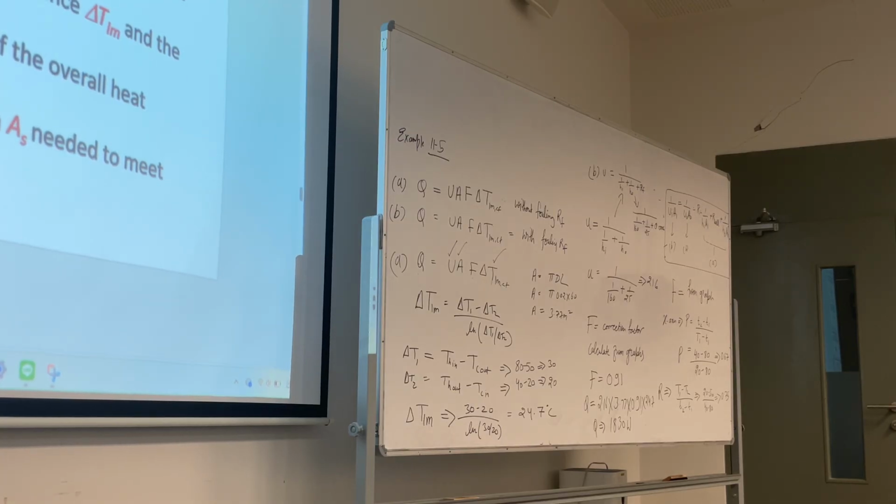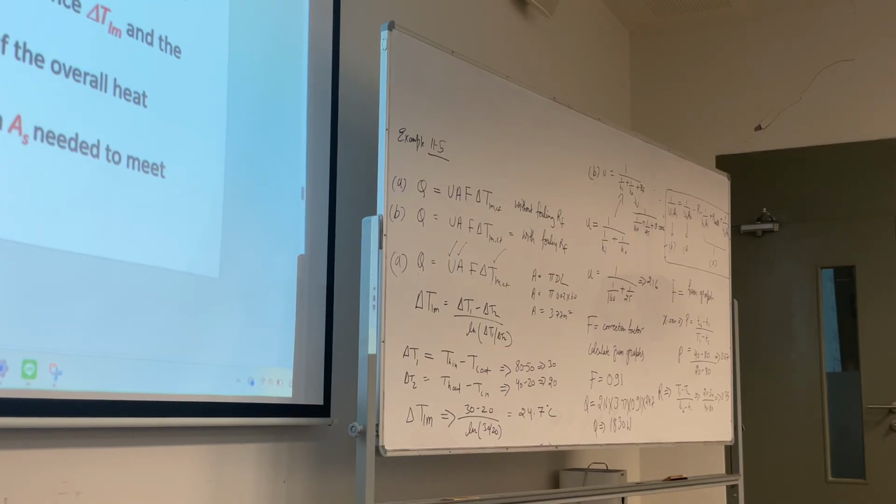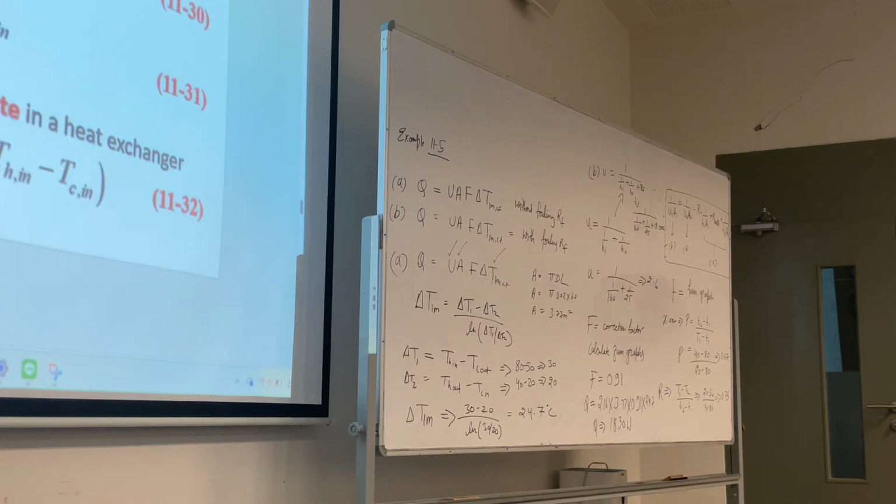So when you read the question, and in the question you can identify one of these points, you use LMTD. LMTD has 2 formulas. One is for counter flow, parallel flow, and the second where you include capital F, which is correction factor, when it's a cross flow shell and tube, those exchangers. Okay. The last method of heat exchanger is when the outlet temperature is not given.